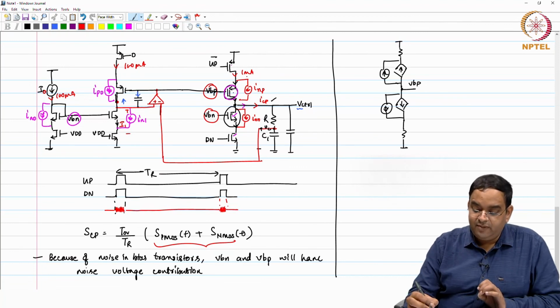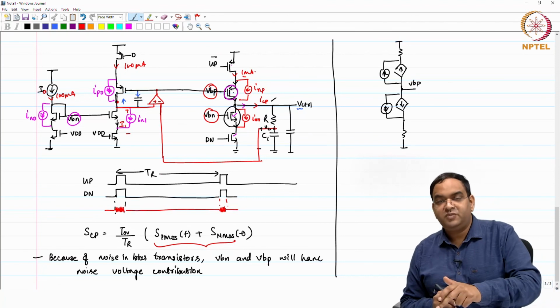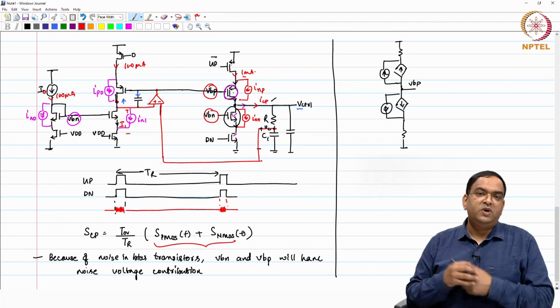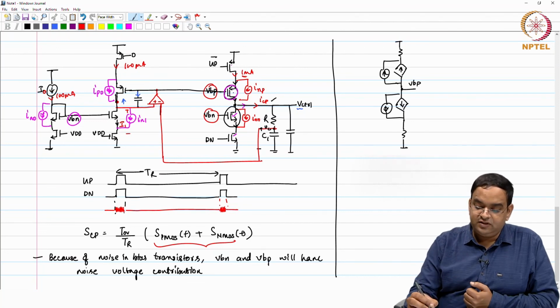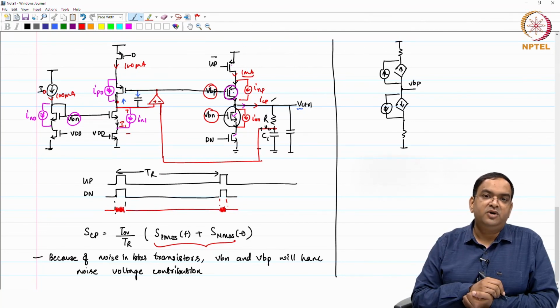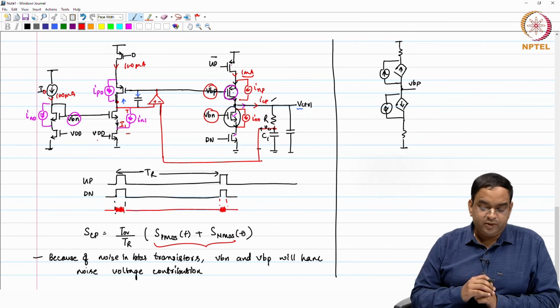From a power consumption point of view, the bias is consuming much less power than the actual charge pump requires. The charge pump current is dictated by, if you remember, the loop gain analysis and the noise analysis. This is the number you will get from your analysis. The bias you will just add to support the actual charge pump circuit.